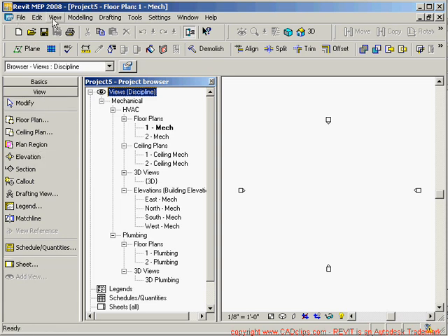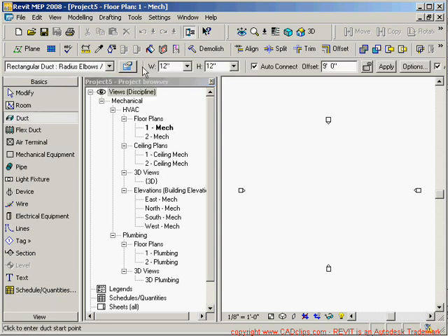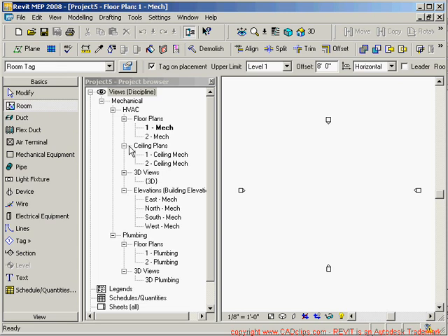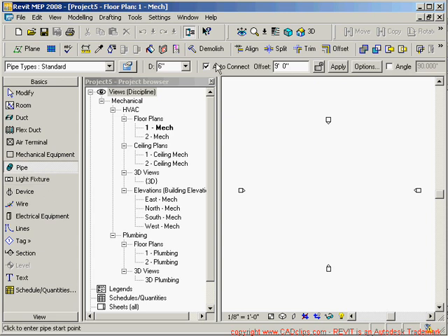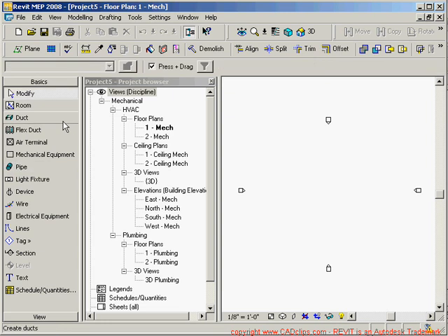These are a lot of our tools which are in our pull-down menus, and we have different tools here, and these toolbars here will change depending on what you click. If you click floor plan, you'll notice that'll bring up a dialog box because of the dots, but as you start to draw, I pick duct, you'll see different options show up here. If I draw a room, different options show up. Okay, you don't have to worry. If you just pick on something, nothing's going to happen. You're just going to see the different options. Okay, and you can go back, click modify, which clears your selection, or you can just hit escape on the keyboard. So we have our basic mechanical options because this is MEP.